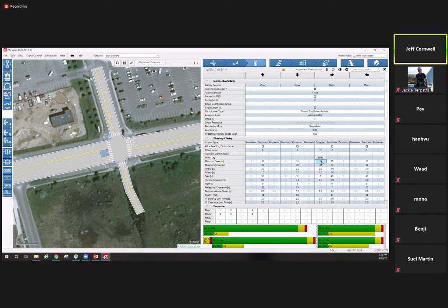So we said, I think that this one should have a min green of 7, I believe. And you've got to make sure too that this is not in the same order as your chart. So don't just go by your chart. You want to actually look at each phase. So if this is phase 4, I think the amber time we wanted was 3.7. Then this one was 4. Oh, sorry, this one was 3.7 as well. 3, 4.2, 4.2. This was, I think, 3.2, 3.2.